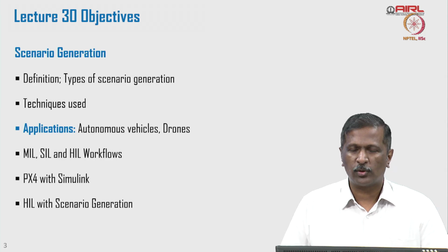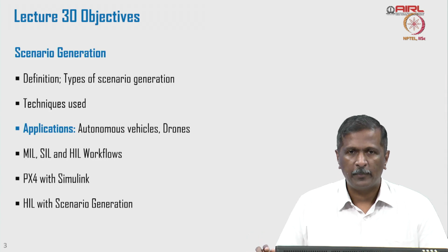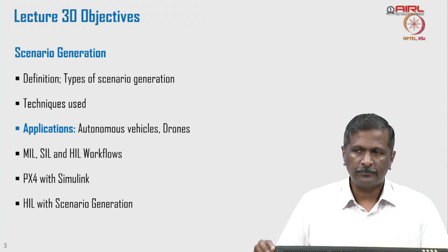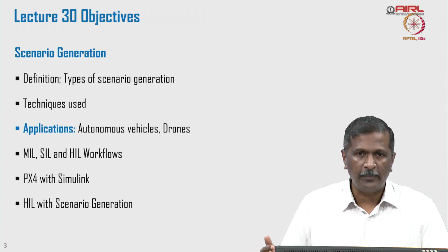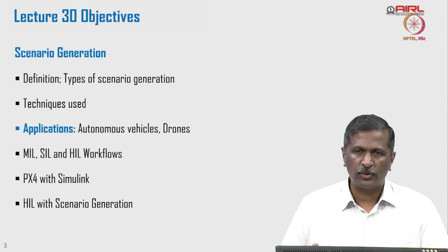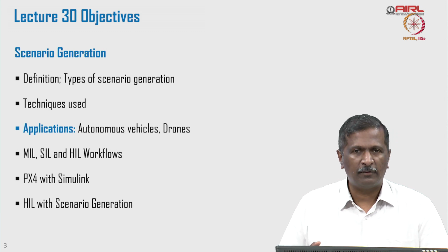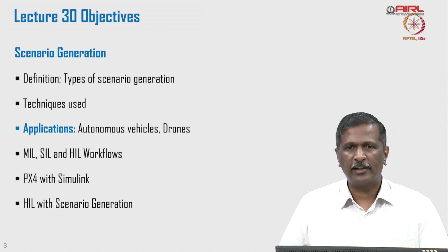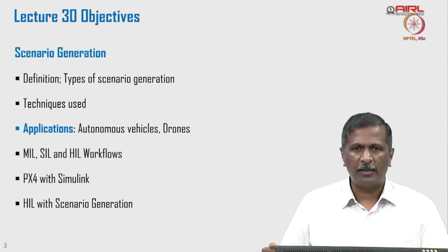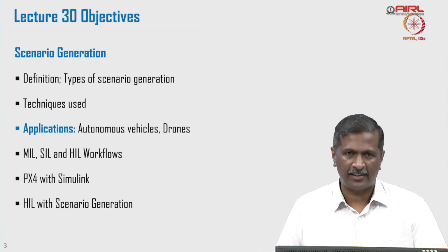Hardware here could be a drone kept at an altitude bench. The drone doesn't have to fly, right? I can simulate the scenario and I can model the rest of the equations of motion in MATLAB, and MATLAB can generate the flight control, and that goes to PX4, and PX4 will just send out the command to the motors, and the motors just spin accordingly and generate the thrust, right?